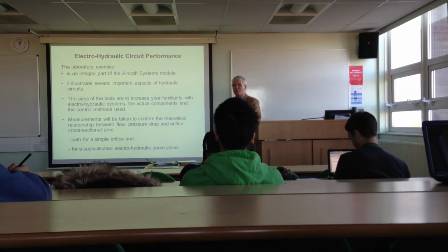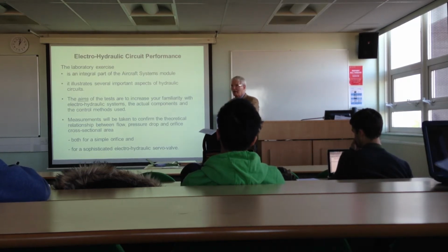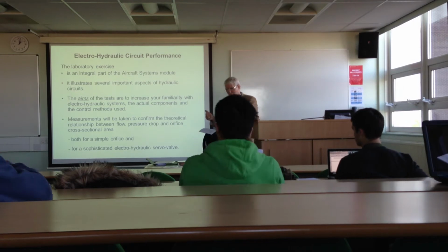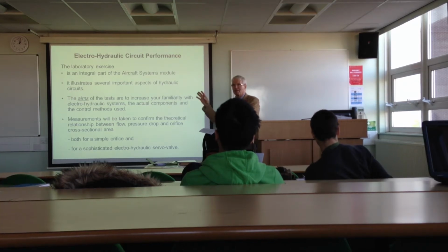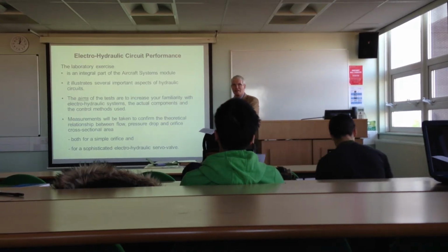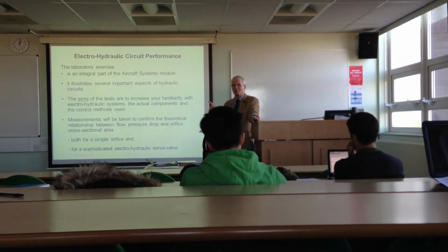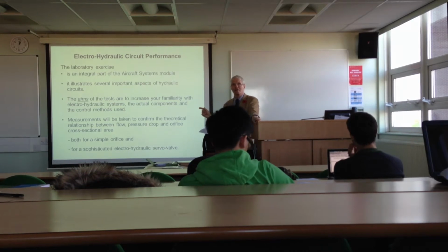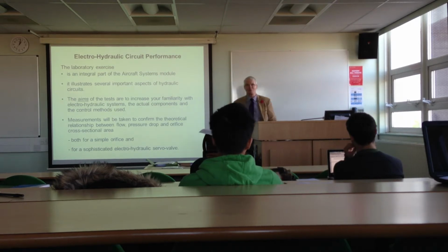I've suggested you've got to be very careful with the results that you saved, because there's a calculation embedded in the PowerPoint, so you've got to be a little bit careful. I've asked you to check that calculation. What I discovered, though, is that between the two sessions, the voltages displayed on the computer screen got switched round. So whereas we thought the first one was the voltage being applied to the servo valve, and the second one was the voltage coming out of the tacho generator, they were actually the other way around. Which meant that you got graphs that didn't look like graphs that we were expecting.